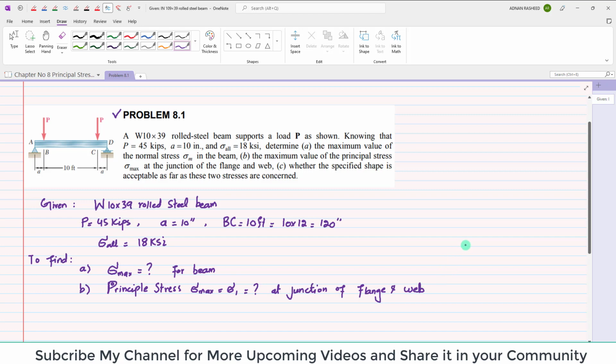If I draw the cross section of this I beam or W, you can see this portion is known as flange and this portion is known as web. Clear? So this is the junction. You have to find the principal stress at this junction.